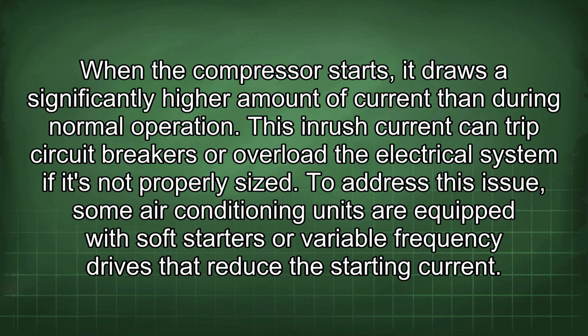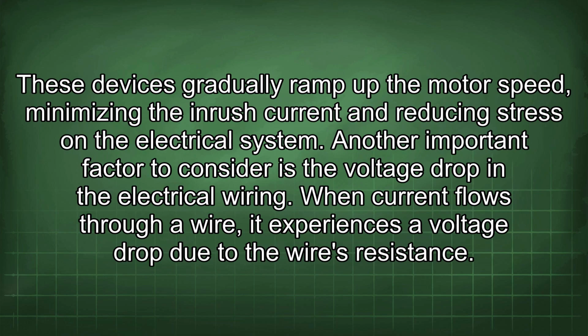To address this issue, some air conditioning units are equipped with soft starters or variable frequency drives that reduce the starting current. These devices gradually ramp up the motor speed, minimizing the inrush current and reducing stress on the electrical system.